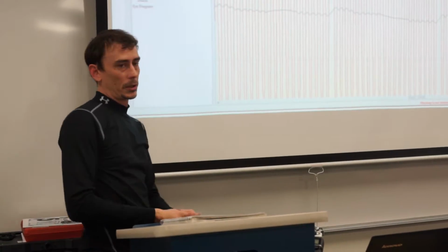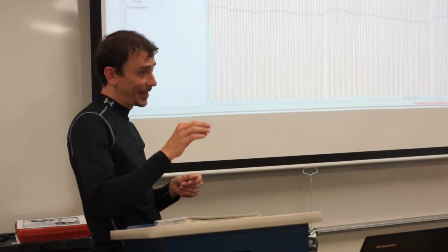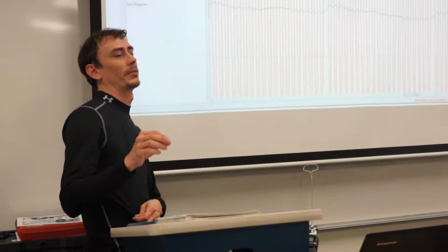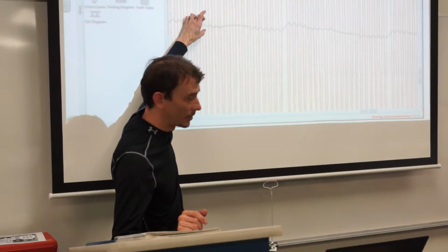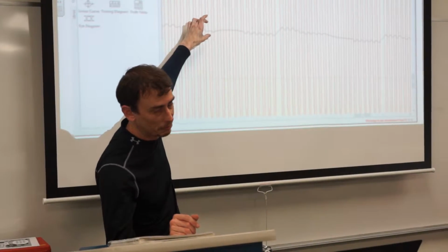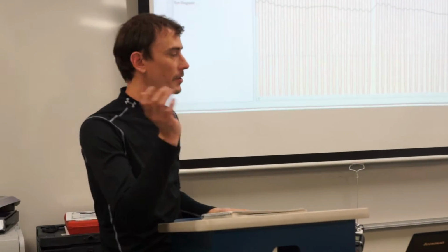So in the real world, it's pretty useless to design a system where you can decide in steps of 19 millivolts what voltage you want out. But if you're getting noise that's bigger than 19 millivolts varying, you've got a useless device. You're within several steps of range.